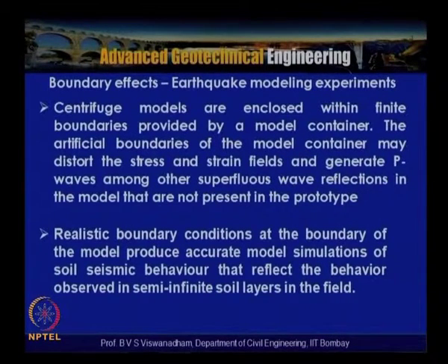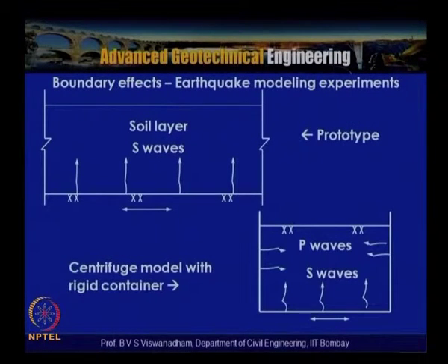So in the prototype, you typically will not have the reflections because of the infinite boundaries, but in the model, because of the confinement with very stiff walls, like in a rigid container, there can be generation of P waves and also reflection of other superfluous waves. So realistic boundary conditions at the boundary of the model produce accurate model simulations of soil seismic behavior, that is, they reflect the behavior observed in semi-infinite soil layers in the field. So this is what has been discussed.